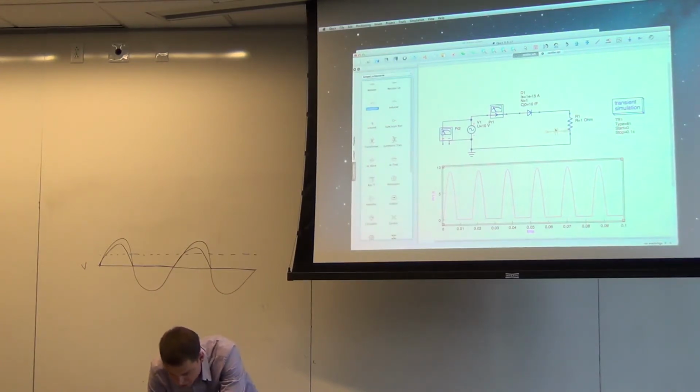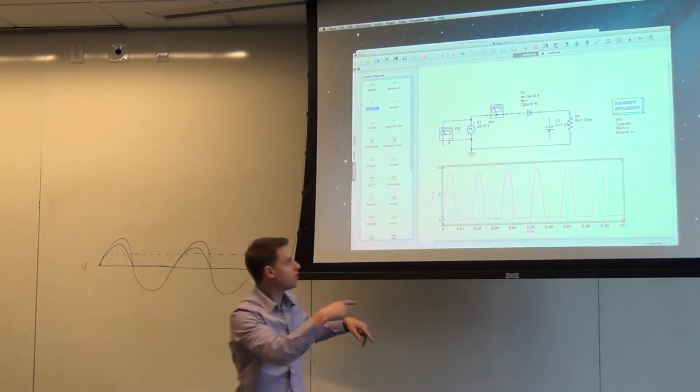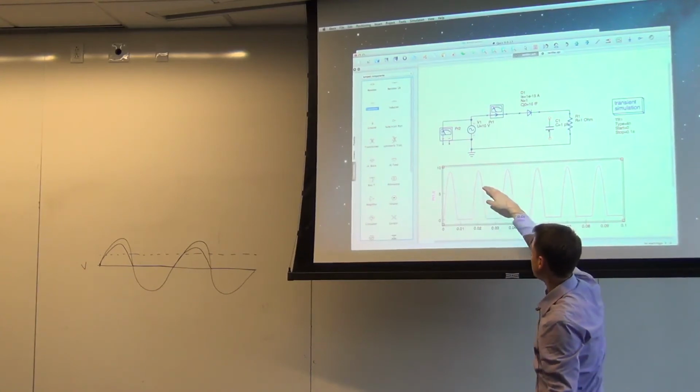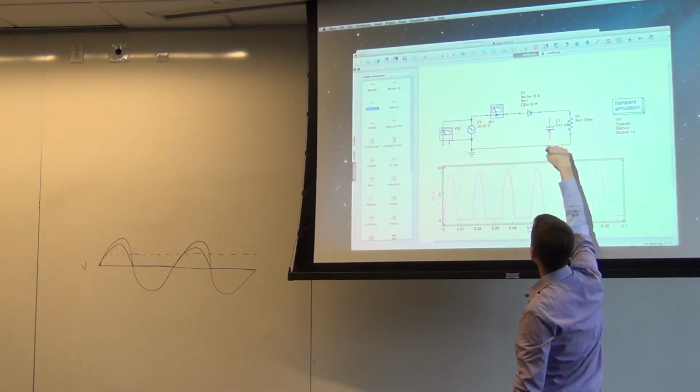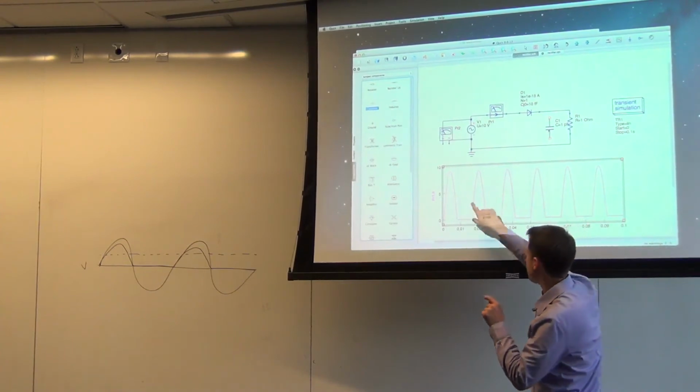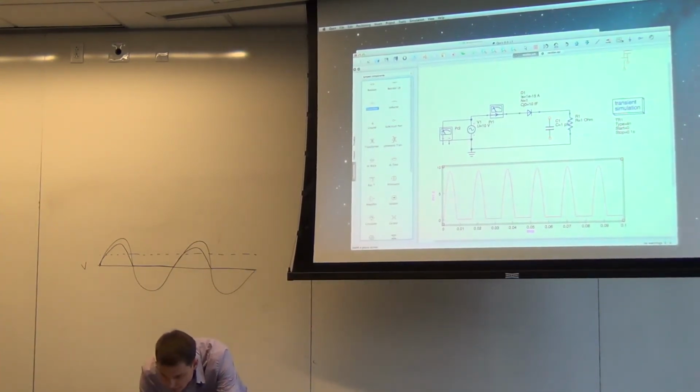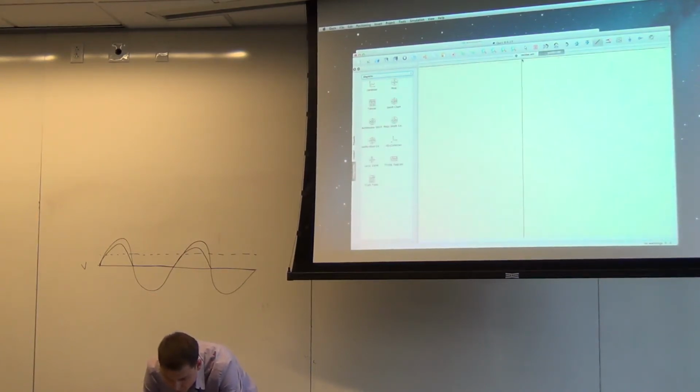capacitor. And as I said, what the capacitor is going to do is build up charge when current is flowing here. And then when it's not flowing, so when we're down here, it'll let current supply voltage to the thing itself. So it'll essentially take this and average it all together. And I think like 1 millifarad should be plenty for that. I could be wrong about that, but let's see. Okay, let's simulate that and see what it looks like.